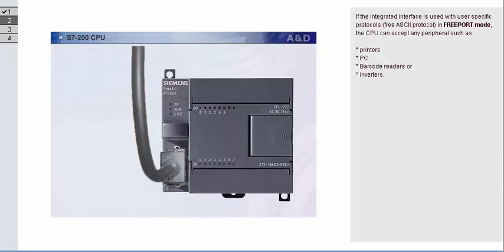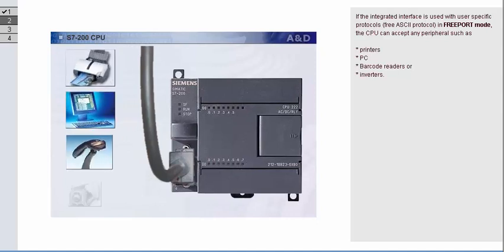If the integrated interface is used with user-specific protocols, free ASCII protocol, in FreePort mode, the CPU can accept any peripheral such as printers, PC, barcode readers, or inverters.